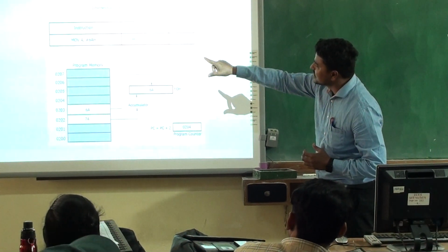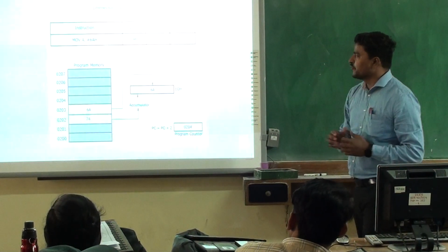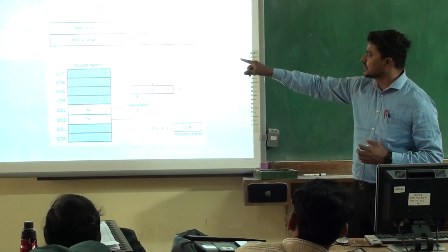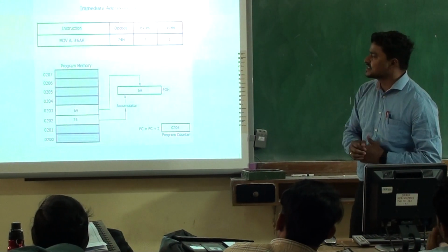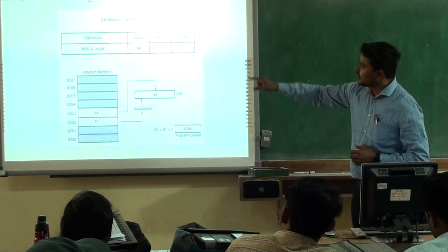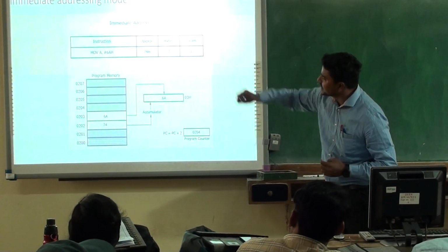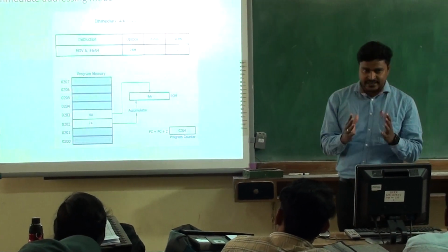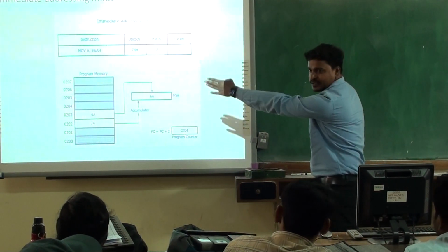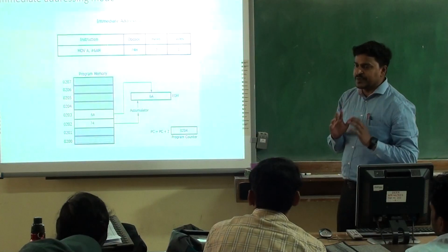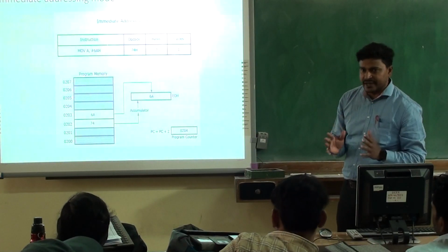As we can see, the instruction written is MOV A, #6AH. The H shows that the data is in the hexadecimal number system, and the # shows that this is immediate data, an immediate constant. We are not changing it. We are just putting it right there, and it will be transferred to A, which is a special register called the accumulator.